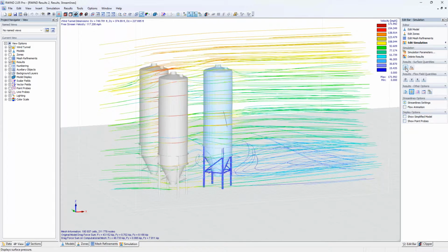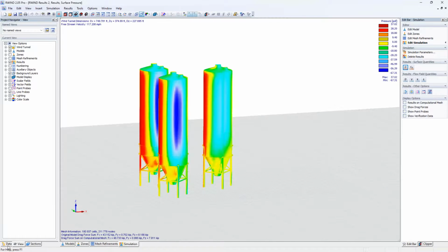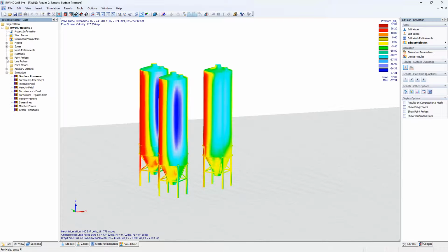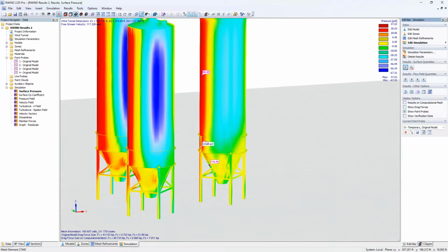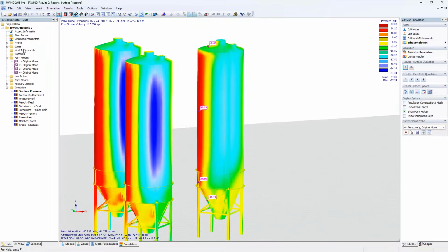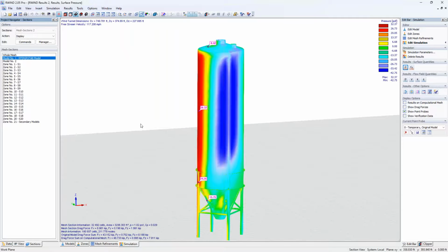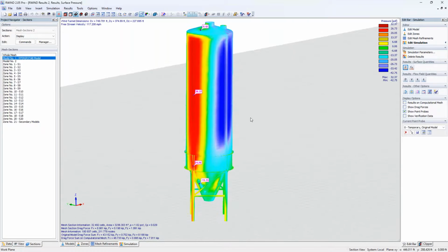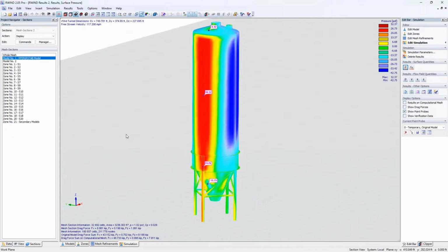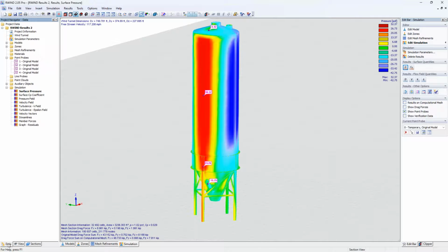So going back to the pressures here, under the data tab, remember how we have just set those points back in RFEM for the experimental data. These are now inserted here as point probes. So you can see those 4 point probes given to me at those particular locations, and they're available here within my navigator. And under my sections tab, I'm going to go ahead and only activate here the RFEM model so that we don't need to worry about the view of those additional IFC objects. But currently those point probes, again, the same points that we generated in RFEM, are just showing me my pressure